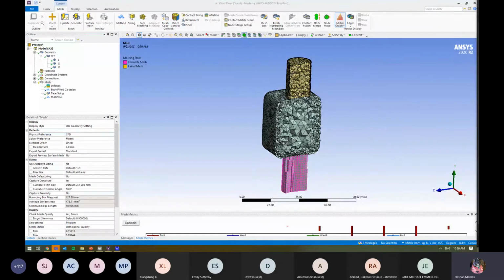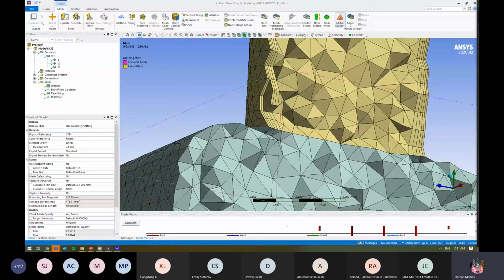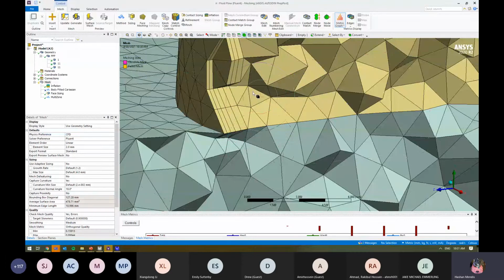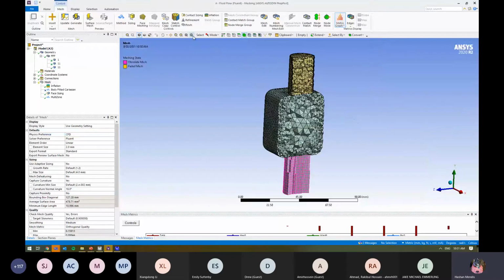And the difference between shared topology and partition. With shared topology, we're enforcing a shared boundary between the two nodes. I'm assuming if it's partition, so if it's not connected whatsoever, it just again means we've got a mismatch between the two surfaces. And if we've got problems, we can sometimes have interpolation problems as well between there. There are instances where we've got a sliding mesh where we don't want nodes that are perfectly aligned. We still want a similar face sizing, but it allows us to physically move the mesh and move it around.